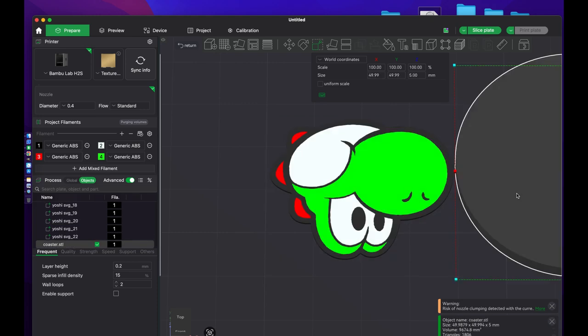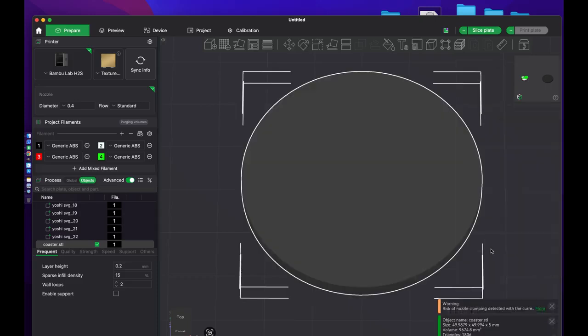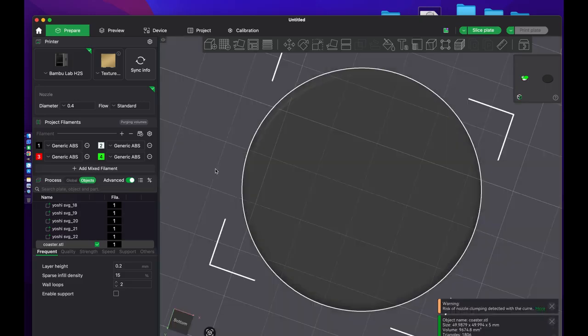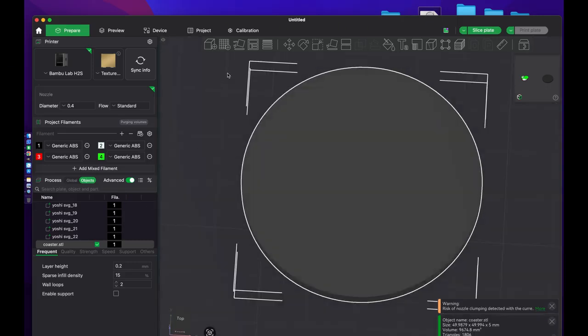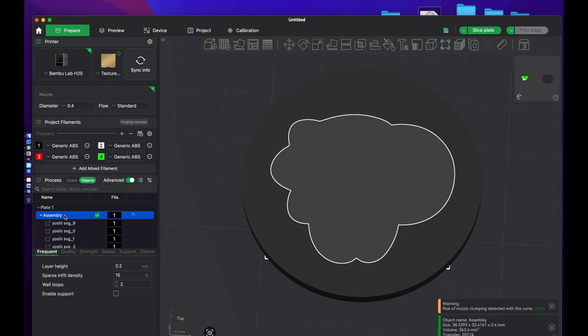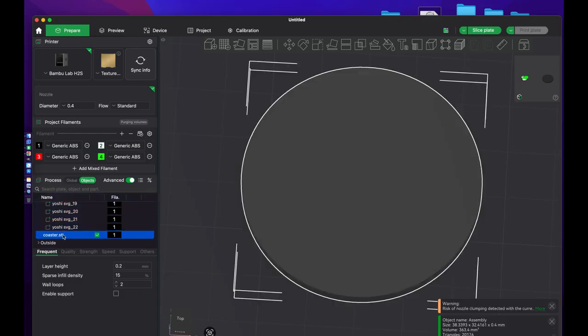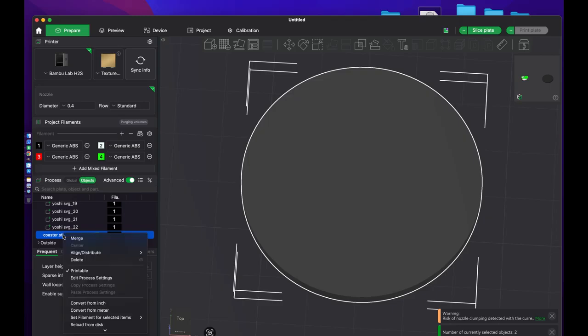and we're going to select it, and we're going to center it back. Now the last step, right before we slice and get ready to print, we want to select both objects here. So you can go over here to this objects menu, click assembly, and go all the way down here, hold shift and click coaster and assembly, then right click and merge.